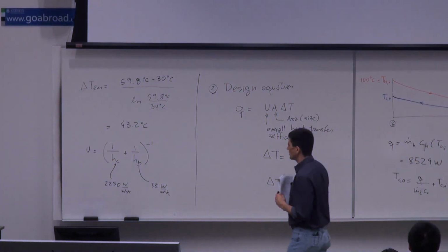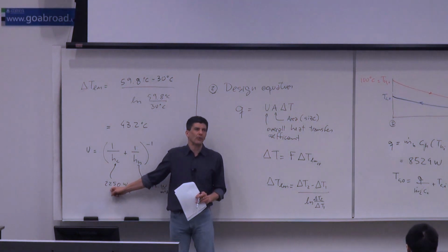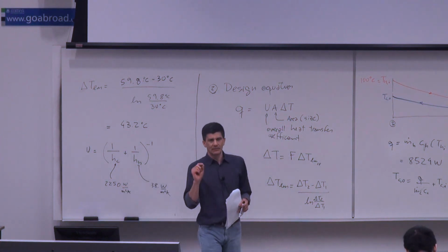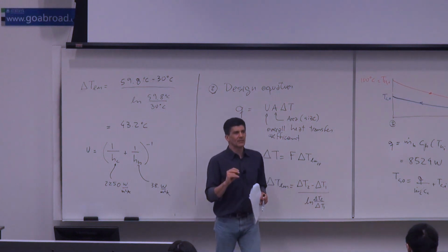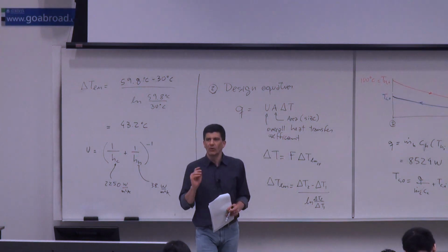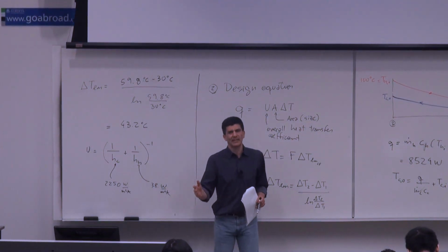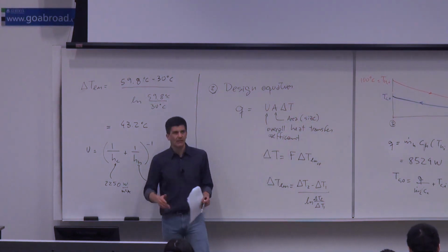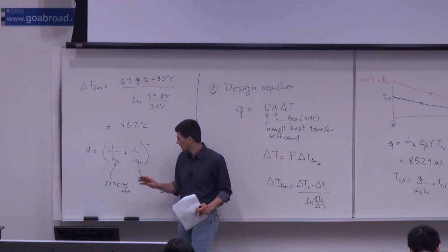So, for example, if I put fins on my cold fluid, what do I gain? Nothing. And just pay attention to me for a brief second, because this issue of dominant resistance matters so much. In industry, you have all the time people who say, well, how can we make this heat exchanger better? And they would say, oh, well, the book says put fins. And fins in water is good because it's not going to get fouled. There's many good reasons to put fins.